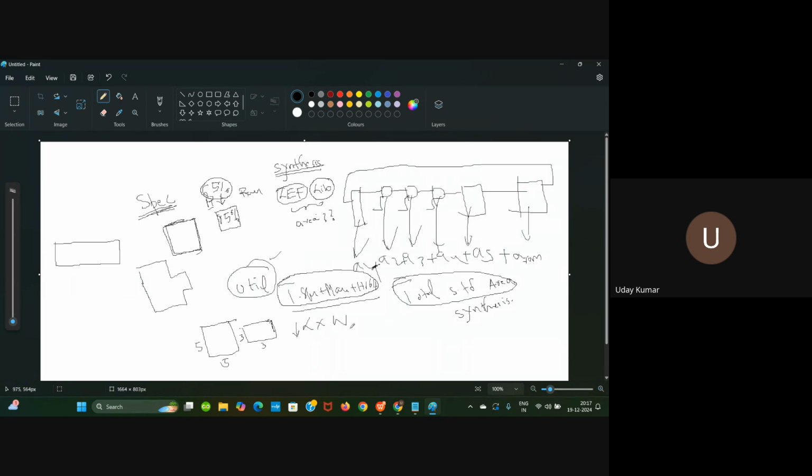Another sort of area optimization is, let us say you can't shrink it anymore because you have a PCB. The PCB guys will do some iterations over this area and fix one final area. If you can't shrink it anymore and you are getting lots of violations because of these standard cells, then you need to reduce the area of the standard cells.